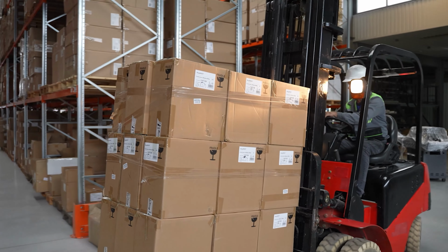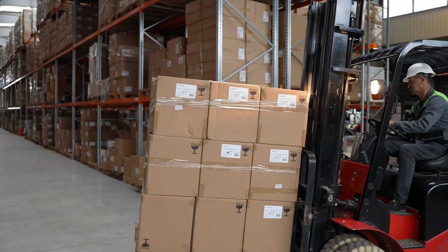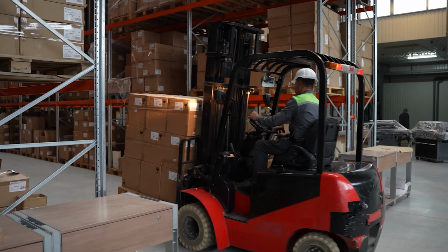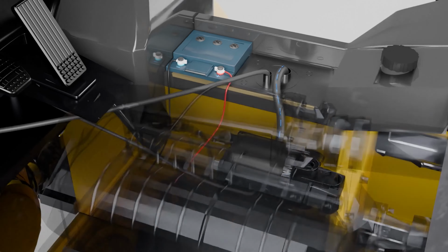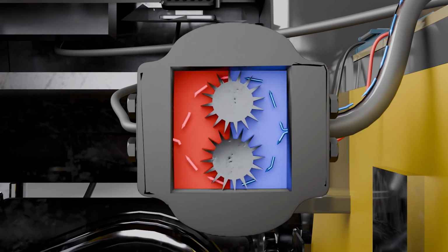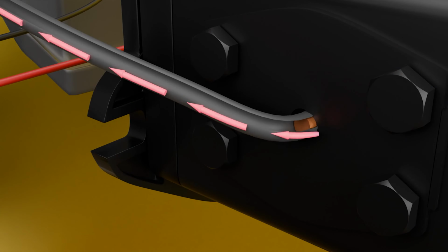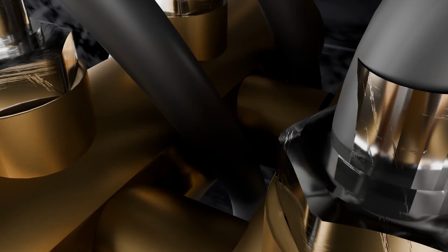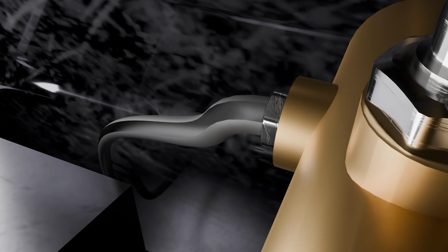Now that we understand the basics, let's walk through the entire hydraulic cycle from start to finish, from the moment the operator moves the lever. When the engine starts, the hydraulic pump begins pulling oil from the reservoir. The oil moves through the suction line, through the pump gears, and out toward the control valve block. At this point, none of the hydraulic levers are being touched, so the oil has nowhere to build pressure. Instead, it simply flows through the valve block and returns to the tank in a low-pressure loop, waiting for the operator to make a command.